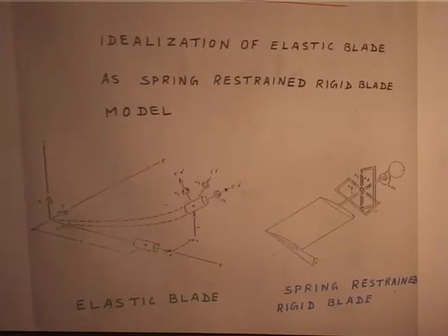Okay. You try to match the fundamental natural frequency of the blade, only the fundamental first mode, because an elastic blade will have infinite natural frequencies, first mode, second mode, third mode, fourth mode, etc. If you study vibration then you will know. Otherwise you know a spring mass system, you have one spring mass, single degree of freedom, one natural frequency. If you have 2 degrees of freedom, you have 2 natural frequencies, 3 degrees of freedom, 3, infinite degrees of freedom, infinite natural frequencies. Okay.